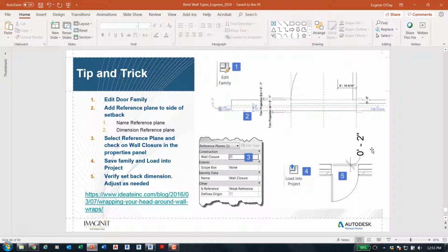Sure. When you export, say, a wood frame wall to AutoCAD and give the structural engineer their AutoCAD drawing, it shows you just the wood layer, the siding layer, and the structural only needs really the stud layer. You just turn that off and AutoCAD drops the two outer layers to make it easier to look at? Okay, so refresh my mind, folks. If I set my level of detail to coarse and export out to CAD, I'm just getting the two lines, correct? The finish is what you're saying, okay. And you want the stud. Carl?